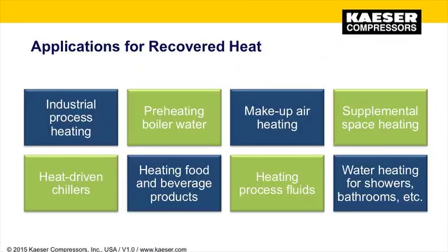Too often, the heat is simply ejected into the ambient environment through the compressor's cooling system and wasted. As we mentioned, nearly all this thermal energy can be recovered and put to useful work and significantly lower a facility's energy costs. Here are some of the many applications for using recovered energy from compressed air systems: industrial process heating, preheating boiler water, make-up air for heating, heating food and beverage products, water heating for showers, bathrooms, etc., supplemental space heating, and heat-driven chillers.